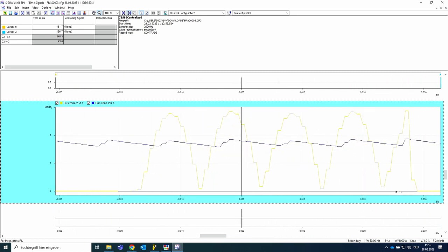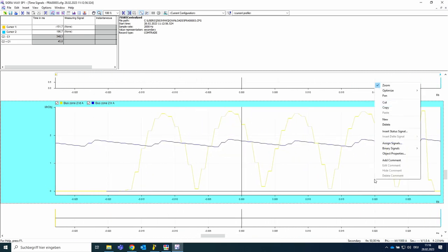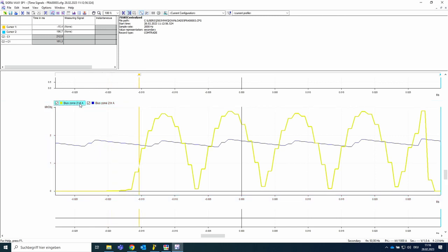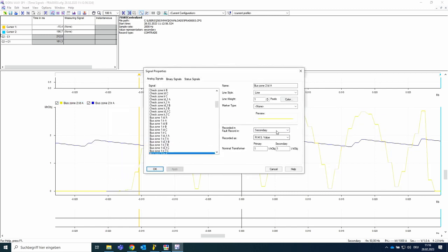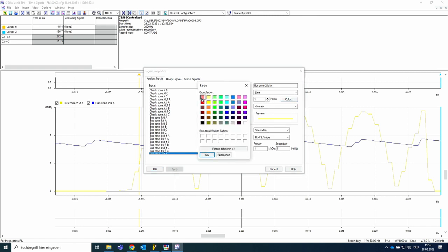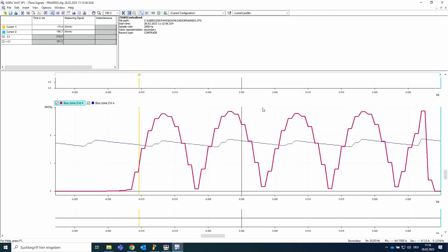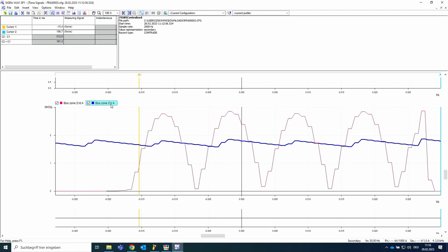So now we can analyze the 2 out of 2 algorithm. And if you remember correctly, the 2 out of 2 algorithm will be triggered for the first threshold exceeding when the 1 out of 1 algorithm can't apply. That means that we have no jump of the stabilization current.